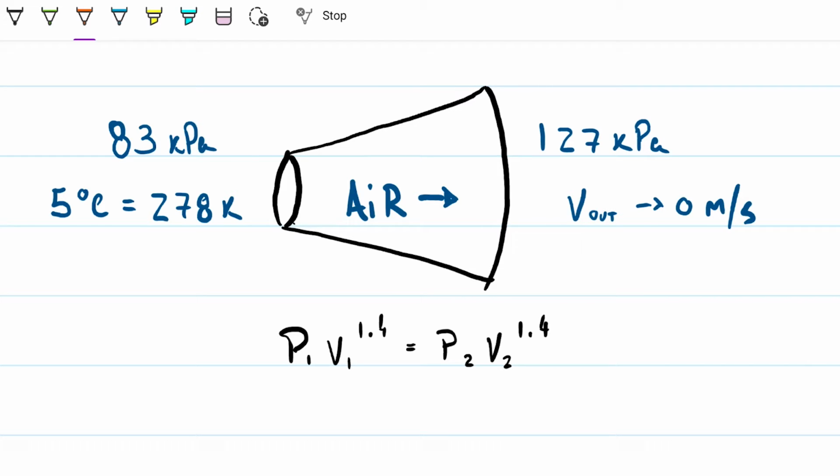Easy to understand. Today we're looking at a problem with a diffuser, which is the opposite or the inverse of a nozzle, right? Whereas in a nozzle, we're trying to convert flow energy, internal energy, into kinetic energy, here it's the other way around. We want to convert the kinetic energy into pressure, flow energy, or internal energy. So the idea is to really stop the air that's coming in so that it comes into a compressor with already a higher pressure and a steadier flow, less chances of having turbulent flow, more laminar flow, all those good things that assist our compressor.